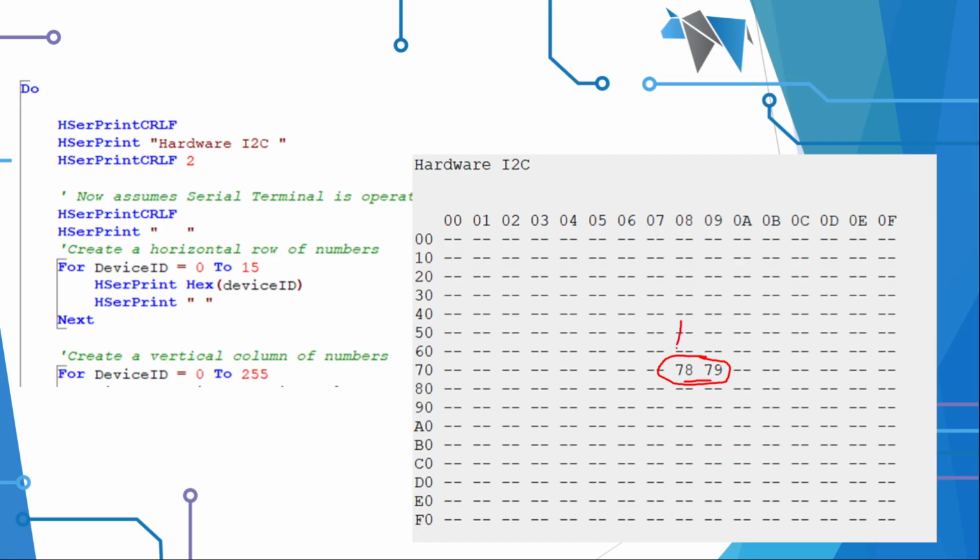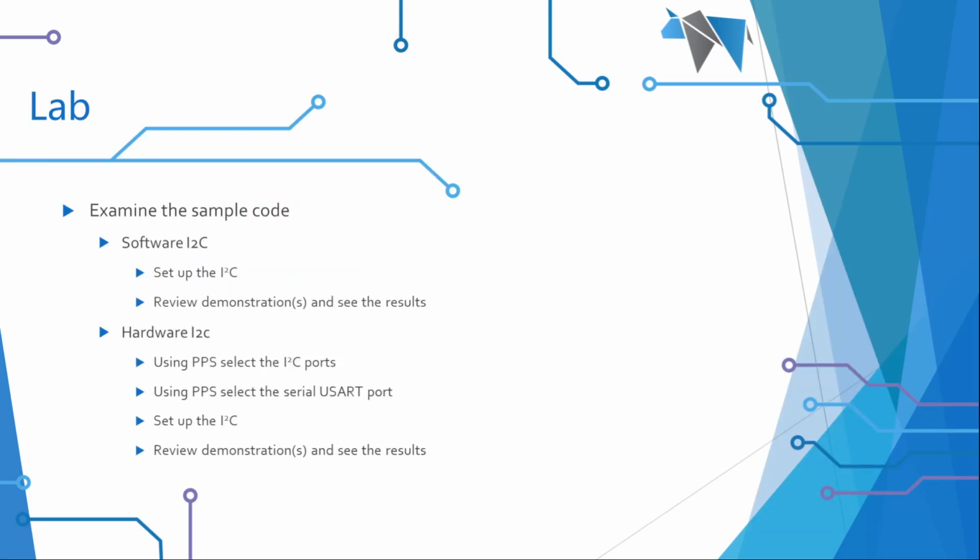And this is the write address, and this is the read address. You might end up with something down here in a 0 range, and that would typically be memory. You know, you could end up with something down here and here, but devices have all sorts of numbers, and you need to ensure that you can see those and address them, because if you just send data out, you're going to get very frustrated. So discovery is a critical part of the process.